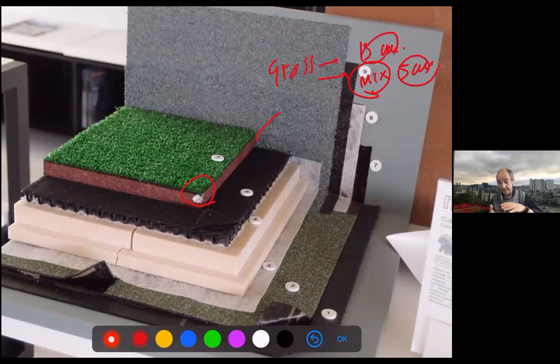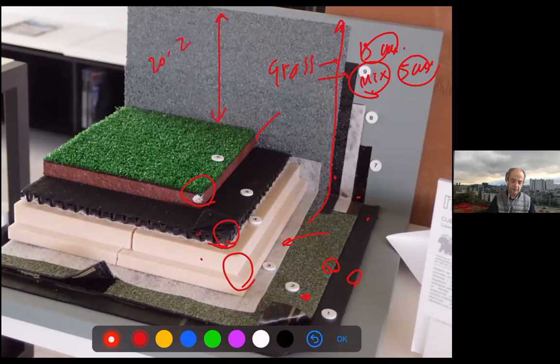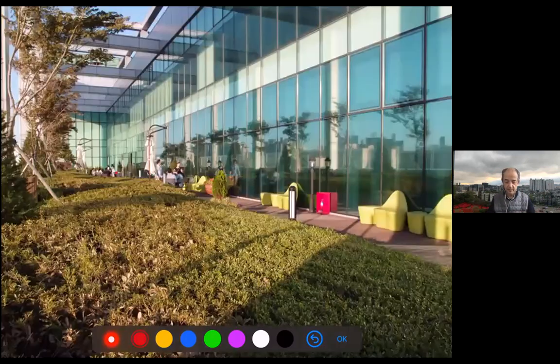So you make it lighter and so on. But eventually you have this drainage layer. See the separation felt, so these polymers not touch each other, expanded polystyrene, and then protected separation layer again, this is what we said, and a double layer of, actually triple layer of bituminous finishing. With, of course, one extension in the parapet, you will put always 20, 30 centimeters, as we did in the plinth, right? It's the same case, to avoid that humidity, that splash to damage the walls.